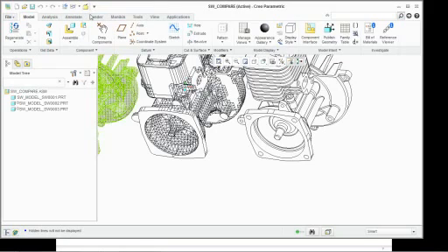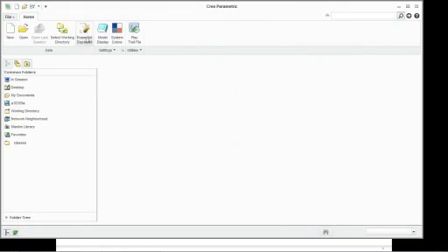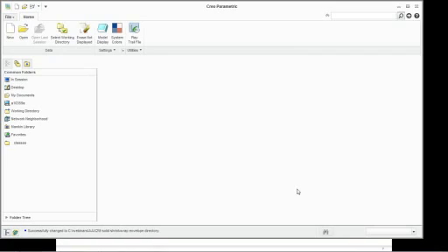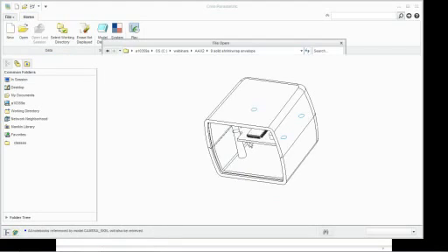So now you're thinking, well, what's the point? Why would I want to use these? I'm going to flip over to another example now. And this is the camera example that I talked about a couple weeks ago. So we're going to select the working directory, and now we're going to say we want to go to solid Shrinkwrap envelope. I'm going to create a Shrinkwrap and actually use an envelope to put it into an assembly. So now we're going to open, and we want to go to, let's see here, camera1.assembly. There it is.